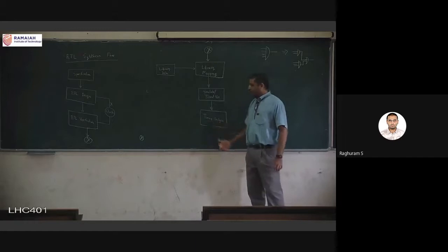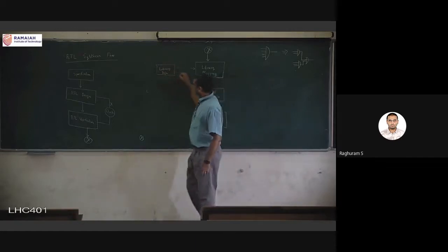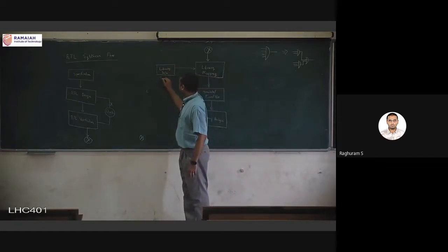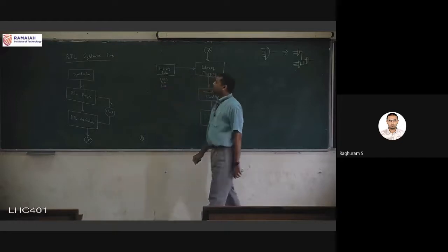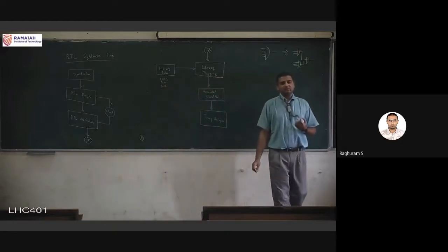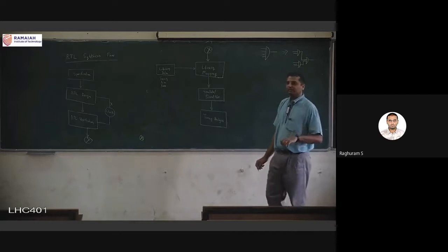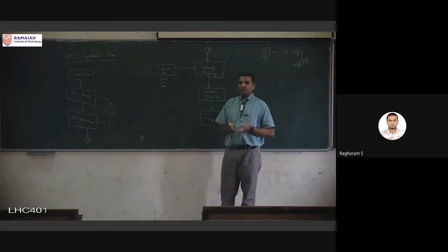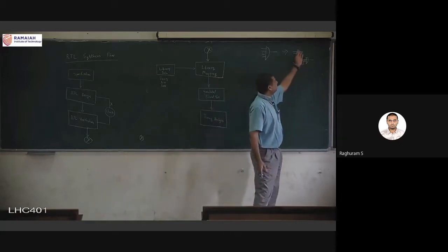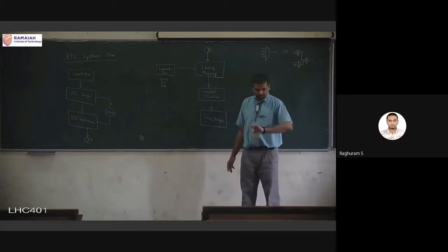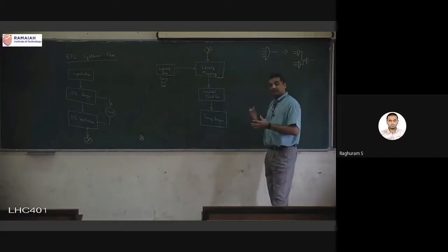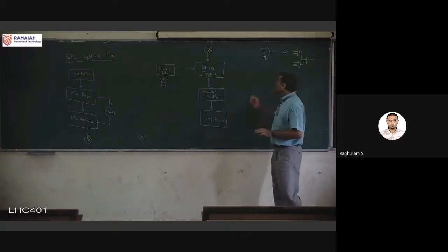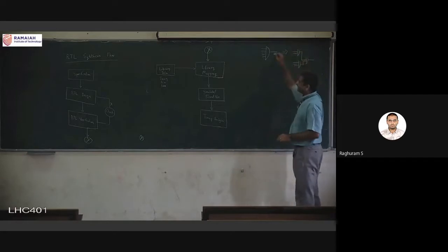How can we do it now? It's because of this library. Timing, area, and power. So these are the things that are also available as part of the library data. It's not just the functionality, it's not just the gate, it's not just the 2 input gate or the 3 input AND gate. It is also the timing, power, and area information of each of these cells.